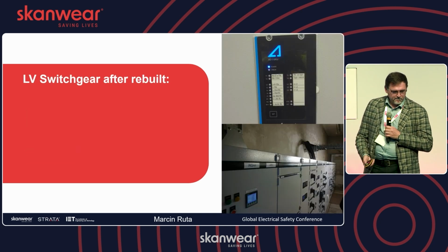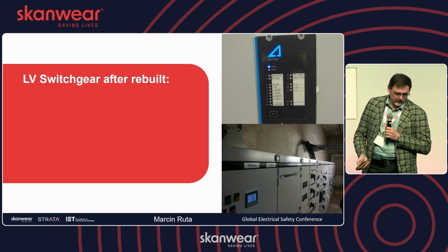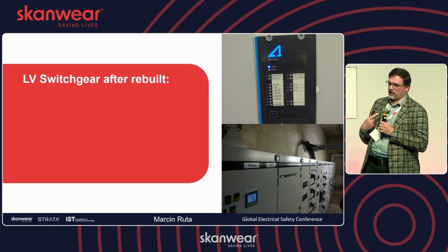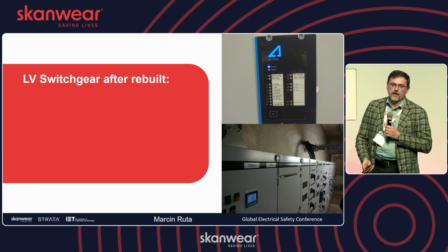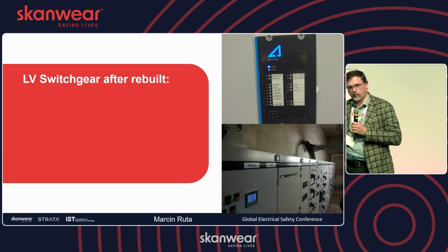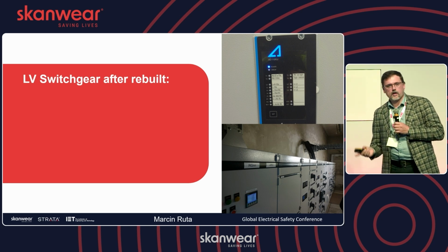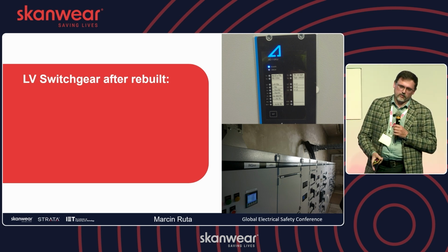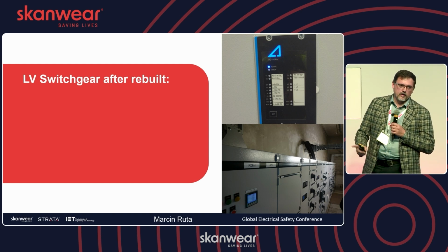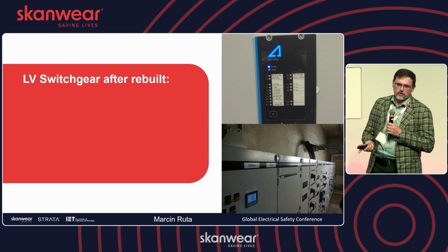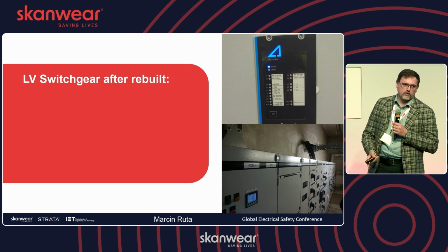What we did, we proposed, but this was actually coming from the customer after our consulting. We proposed that it's probably good to replace the switchgear, but not replace it one-to-one, because it would be a waste of money. We did some calculations. We just found out what we can do. We actually couldn't make it with the protection settings. So we initially proposed arc flash protection, but they also said, okay, let's go with arc flash quenching.